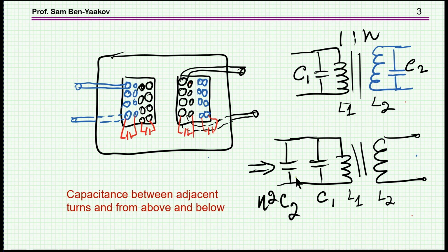capacitances. Now, aside from the capacitance between the turns, we have capacitance between the layers, and therefore the total capacitance can be fairly high. This especially shows up when you have a large turns ratio for high voltage, and in some applications you really have to worry about it because it gives rise to parasitic oscillation, for example in a flyback.